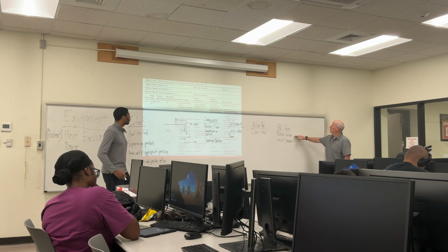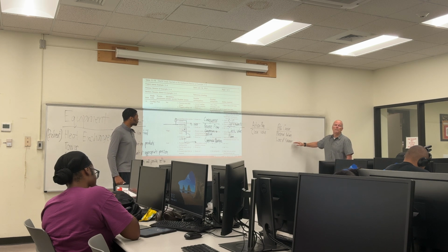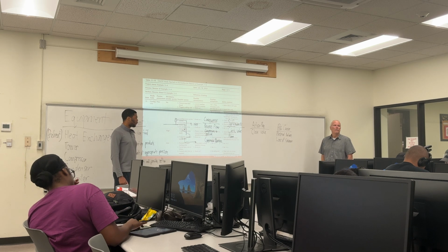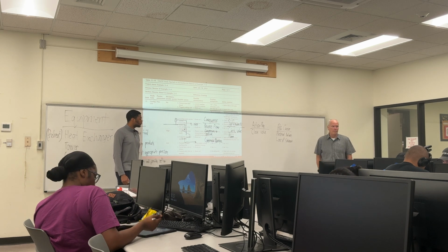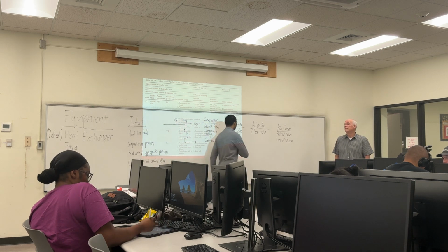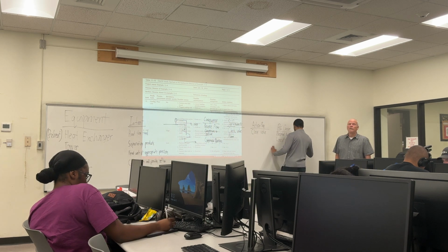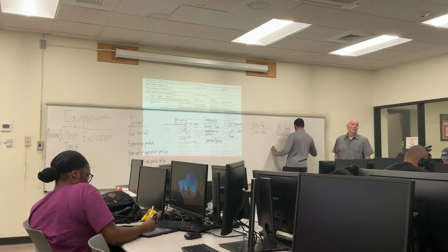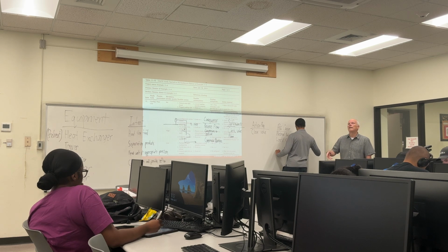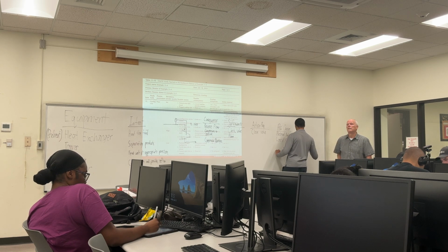So from here, the loss of steam, you might want to say, well, why did we lose steam? Boiler shut off? Yeah, it could be your blower went out. Or if you're buying your steam from somewhere else, maybe they blocked you out. Maybe there was a block valve that closed or something. But you come up with a scenario for it, okay?